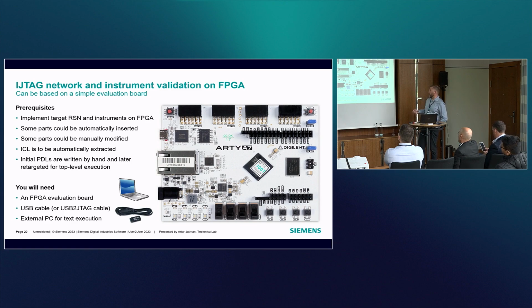In terms of preparation of the actual firmware for the FPGA, of course, there are a number of prerequisites. If you want to work with arbitrary scan networks, then we need a way to implement both them and the instruments on the FPGA. Some parts could be automatically inserted, some parts could be manually modified.